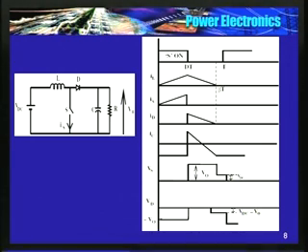So the source current, or sorry, the device current, the switch current also starts from 0. It increases linearly, and when I open S, it becomes 0. Diode takes over. See now the difference here. Capacitor current. I have drawn the capacitor current here.